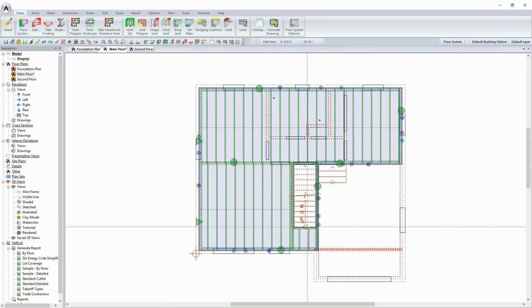So instead of having, say, three 3-foot 2x10s, it would simply calculate one 10-foot piece that you're going to cut into 3 pieces. If you take the time to lay your joists out, not only do you get an accurate drawing, but your bill of materials will run the algorithm to get your cut list correctly.